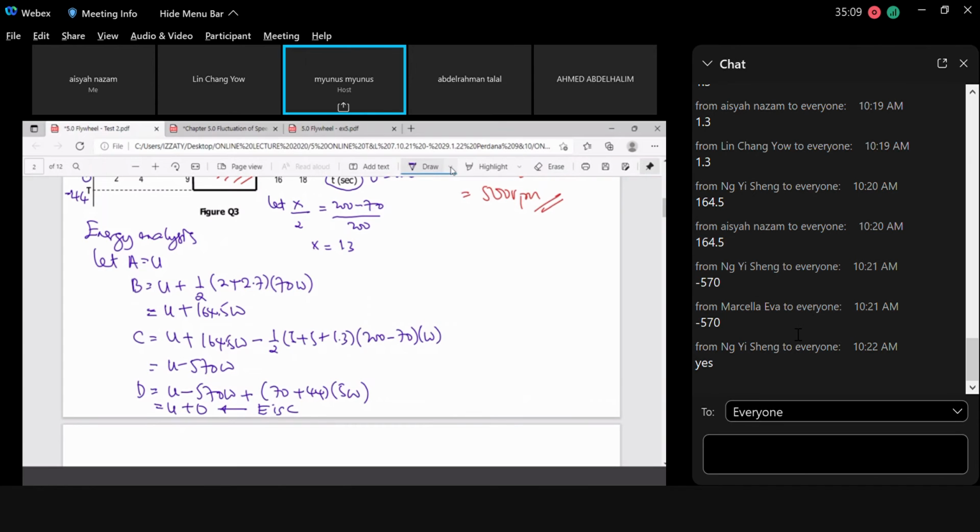So it is not very difficult, yeah. If you basically run through the exercise, it is very easy because you know where you go wrong. So the next point is picking up or selecting all the Emax and Emin. We start with positive. This one is 164 positive. The other one you don't have here, so this one becomes our Emax. On the negative or below zero, we have this one, which is Emin. So finally, your delta E now is equal to Emax minus Emin.